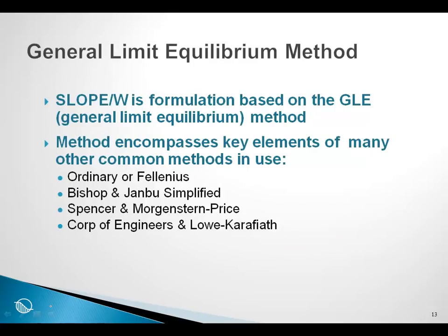SLOPE/W is formulated on the basis of the general limit equilibrium method. We call it the GLE method, and we will talk a lot about the GLE method in SLOPE/W. This method encompasses key elements of many of the other methods that are commonly found in the literature: the Ordinary or Fellenius method, the Bishop or Janbu simplified method, Spencer and Morgenstern-Price methods, Corps of Engineers method, and even the Lowe-Karafiath method.